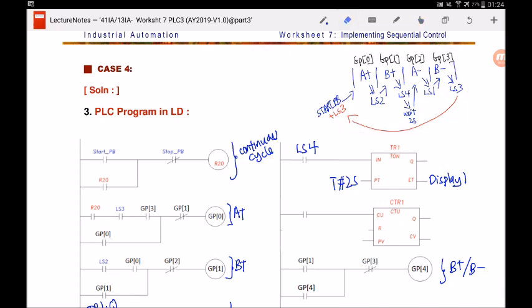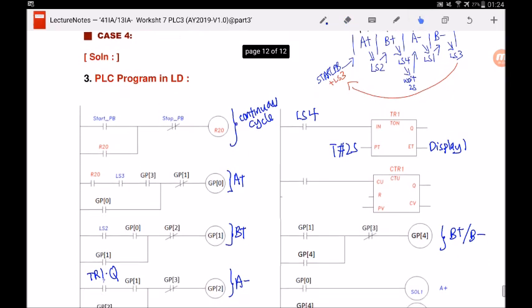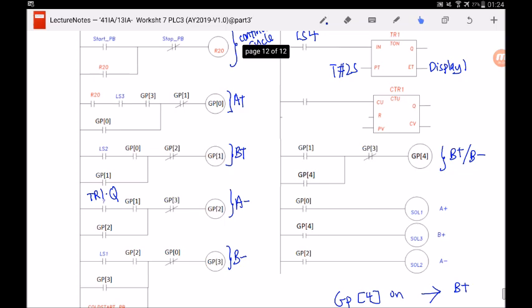Looking at the motion sequence diagram, how am I going to implement counting on the operating cycle? Well, some students will say, okay, can I use GP3 as the input to this counter? In other words, when GP3 is activated, the counter will just register a count once. It sounds logical, because when this sequence is activated and GP3 is on, you want to count that as one complete cycle. That's what most students will propose, using GP3 to trigger the counter to calculate the operating cycle.